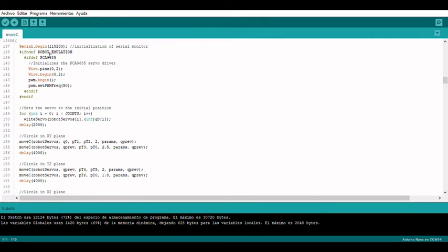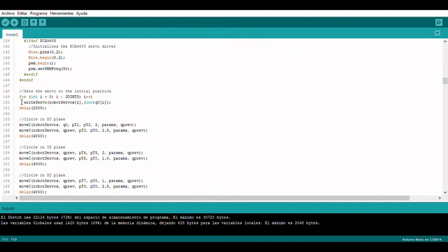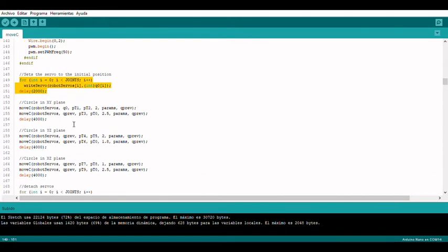So now in the setup, we just start by putting all servos at 90 degrees, and now what we are doing is from 90 degrees to the second point, passing through the first point in 2 seconds, and we store the final position in this vector. Now, again with moveC, from the final position of the previous function, we go to point 3 and back to the initial position in 2.5 seconds, and then we wait for 4 seconds.